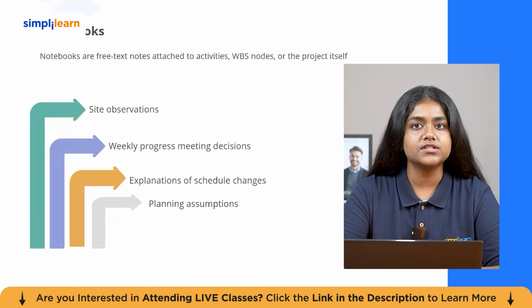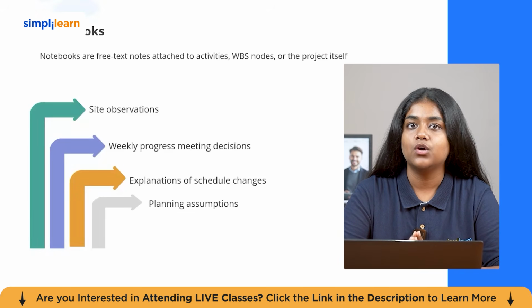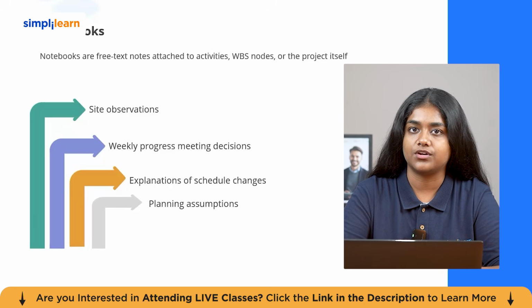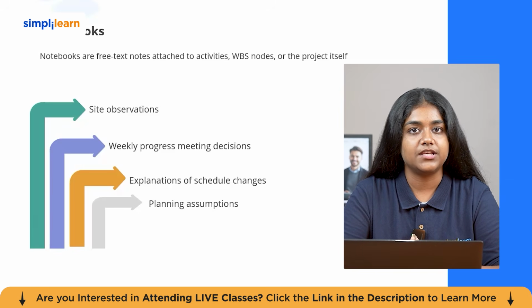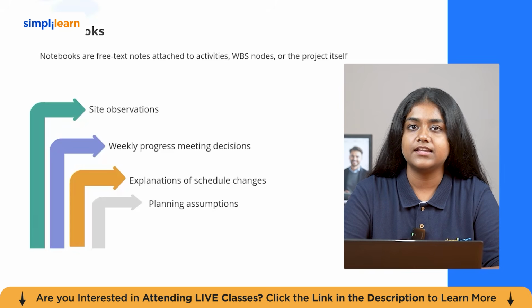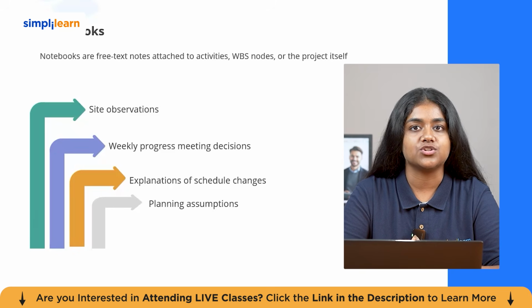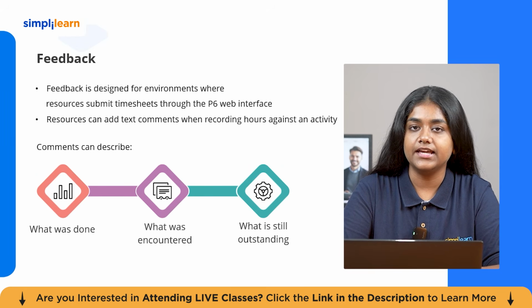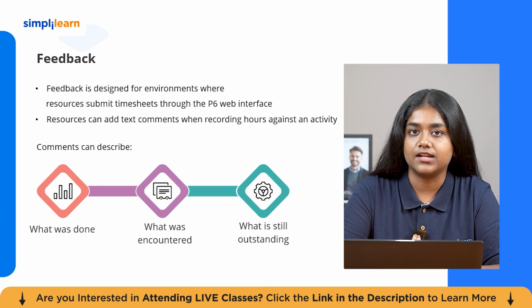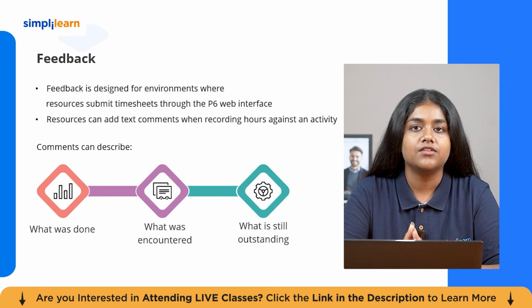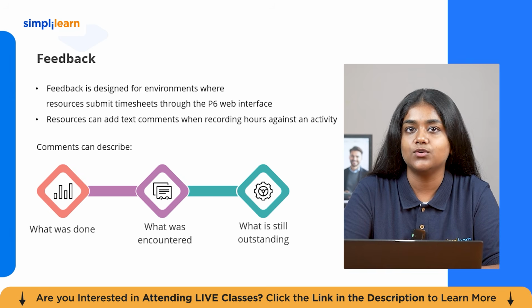So what are notebooks? Notebooks are free text notes that can be attached to activities, work breakdown notes, or the project itself. They are useful for recording planning assumptions, site observations, meeting decisions, or explanations for schedule changes. For example, if an activity duration was increased because of site access issues, that explanation can be recorded in the notebook. This creates useful context around the schedule data and helps future users understand why certain decisions were made. When notebooks are used consistently, they create a narrative record alongside the numerical schedule data. This becomes especially useful during claims, audits, reviews, and lessons learned sessions where the project team may need to explain why certain schedule decisions were taken.